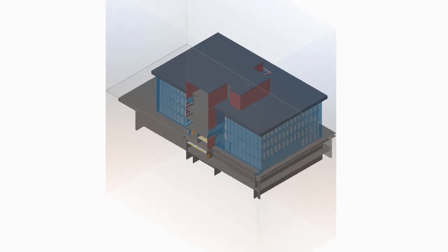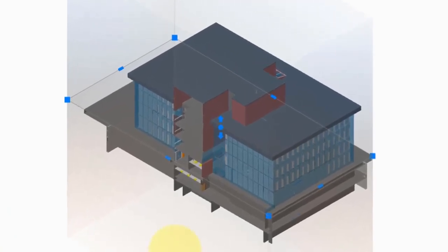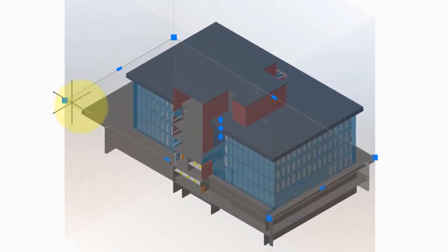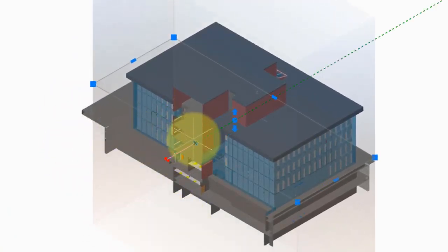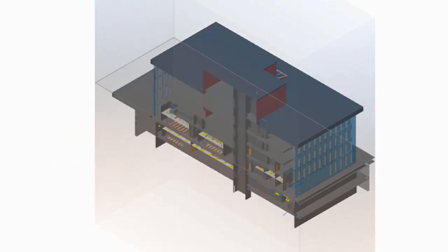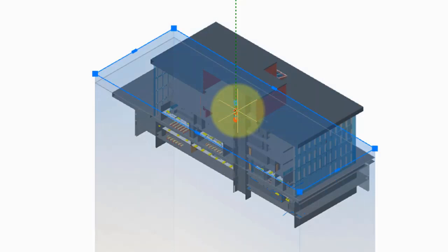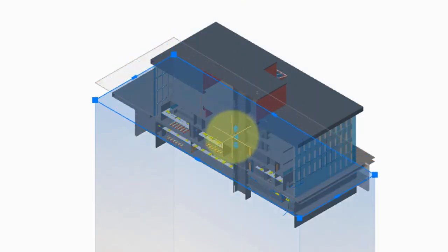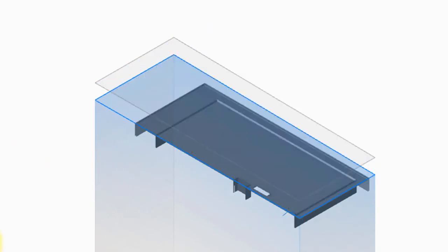To change the bounding prism, I click Modify, and then you can see these polyline grips, which I can use just like a regular polyline. Click Exit to see the effect, and now the building has been partially cut. Now when I click Modify, I'm going to choose this arrow and drag it down a bit, and that lowers the entire bounding prism. And now when I click Exit, the top part of the building is gone.